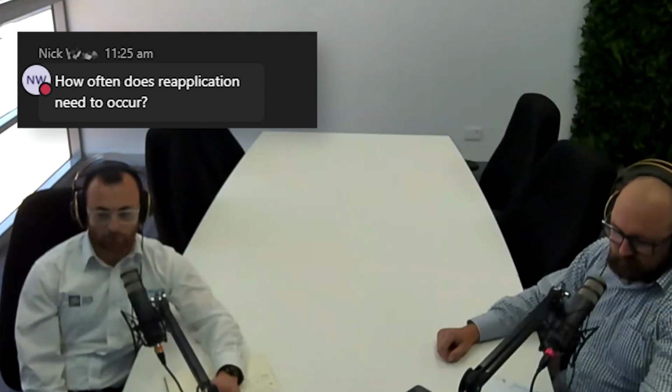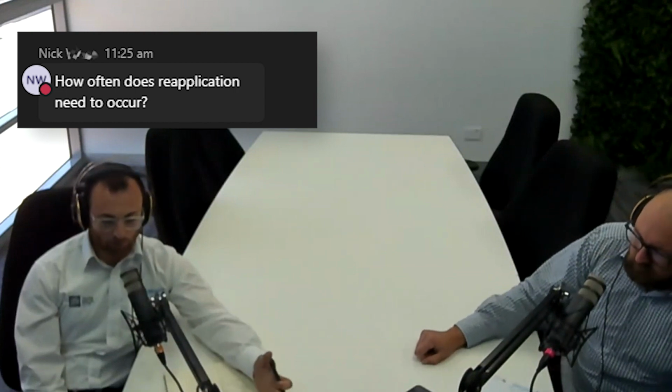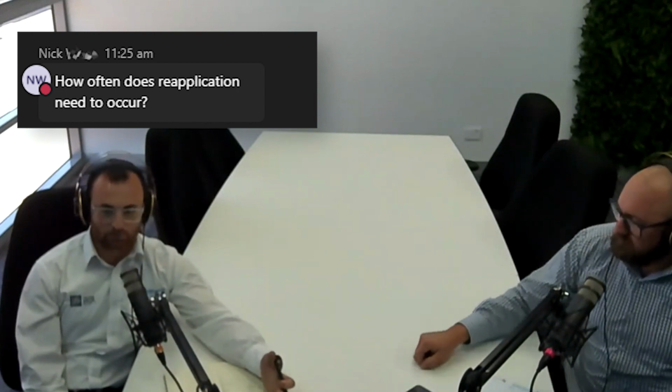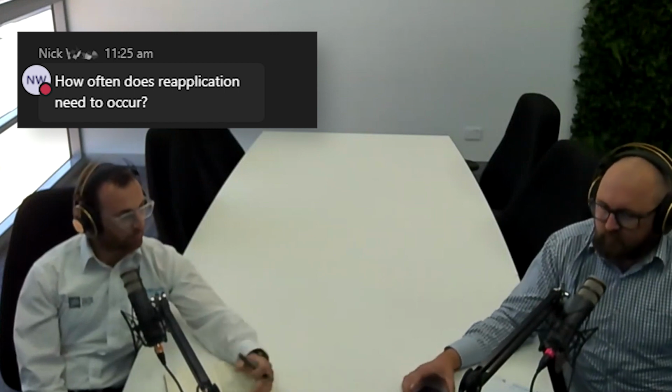Absolutely. And I think you mentioned quite early in the piece that new concrete is the best time to incorporate it. However, it can be done retrospectively as well. You're still getting those benefits from it. The main reason we say new concrete is there's so much moisture in the concrete from new. We can lock that moisture in, which really helps cure the concrete and get really good quality concrete.